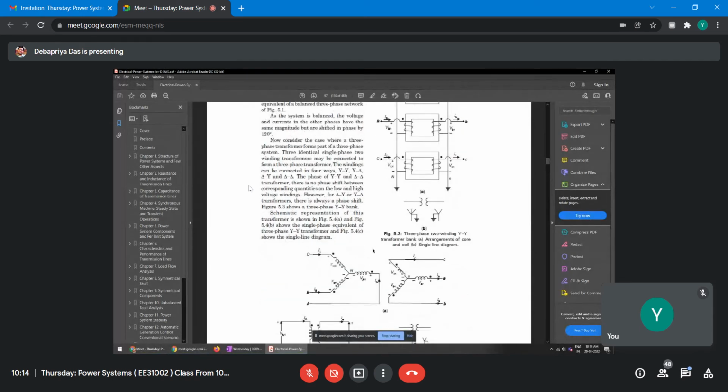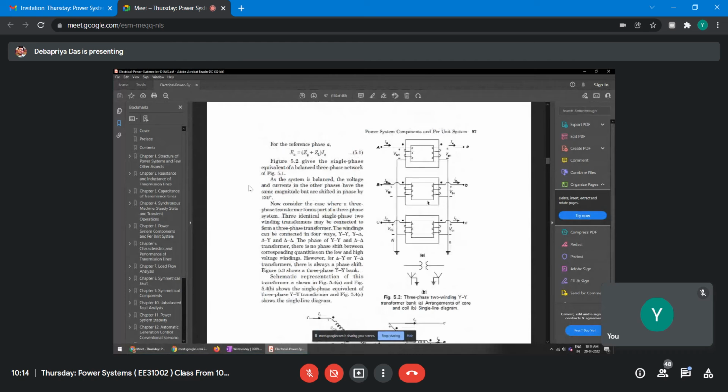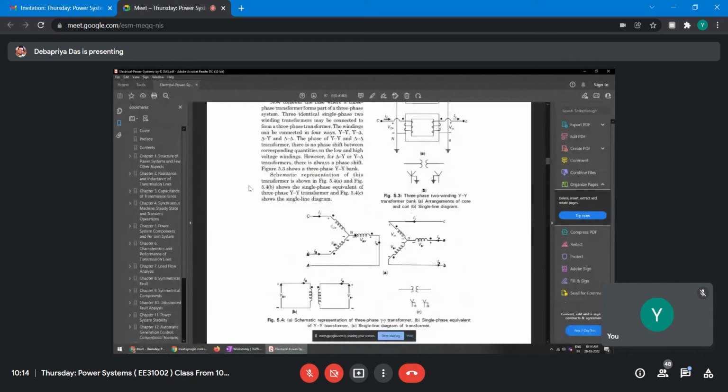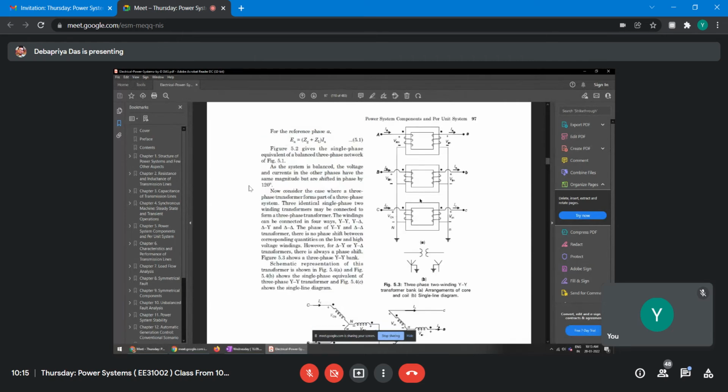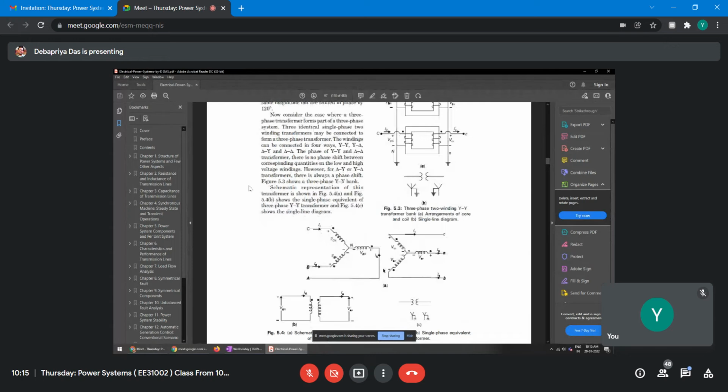This is how it is schematically shown, and whenever you are solving circuit problems, this is how the three phase transformer is drawn. This is the primary side and this is the secondary side. So this way we connect, right? So this is your ABC, and all the currents flow through phases A, B, C, and this is neutral. And on this side also, the way it has been marked, accordingly it is drawn. You can draw it in another way also, right? It is capital N here and small n there, and the voltages are VAN, VBN, VCN.